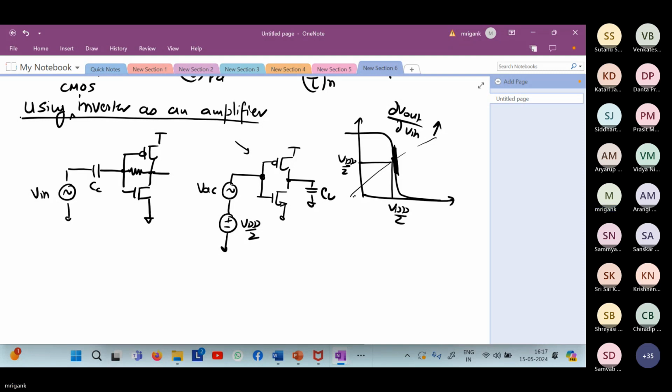So all of us, I think, have discussed this concept of variation. From device to device, the VT of NMOS, PMOS, etc. will vary. As a result, you may not have exactly the same VT, and therefore for different inverters, different amplifiers, the trip point will vary. For the same W by L ratio also, if I include the VT variation in the current equation that we just looked at. In the present scenario, we have assumed some ideal conditions.